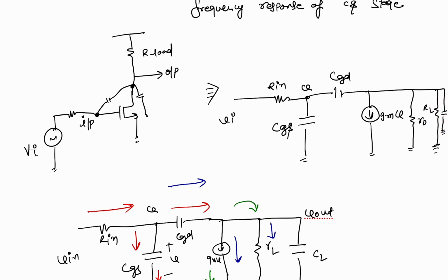But you will get only two poles, because if you write the KVL equation through this loop, one of the voltages will be dependent. Say this is V1, this is V2, then V3 I can easily find through the KVL equation through the loop, because there is no voltage source involved. So I can write V3 in terms of V1 and V2. So this voltage is not independent.